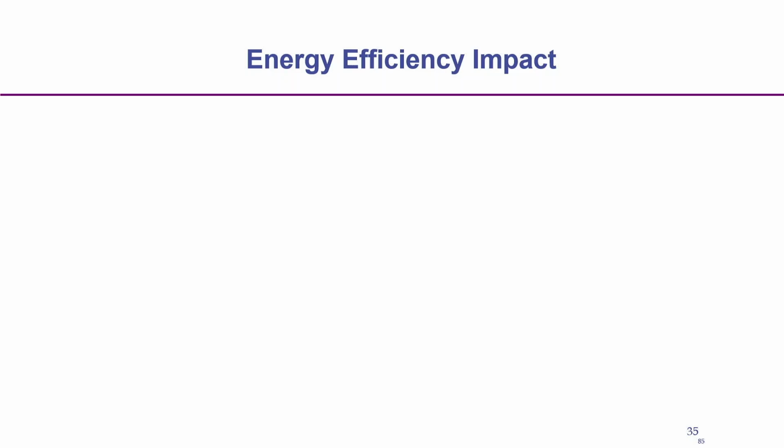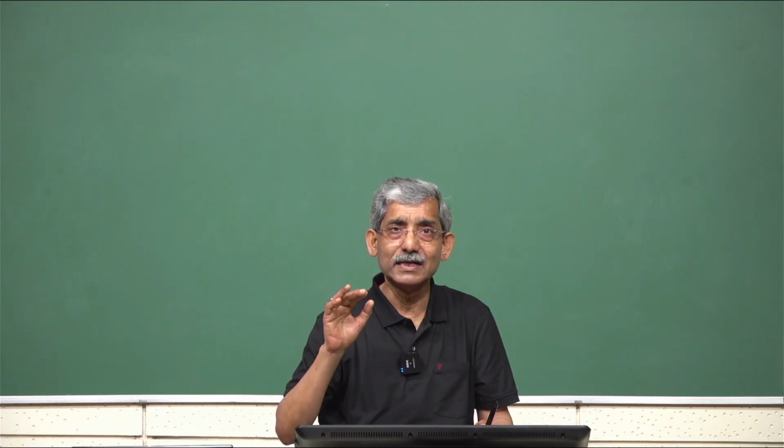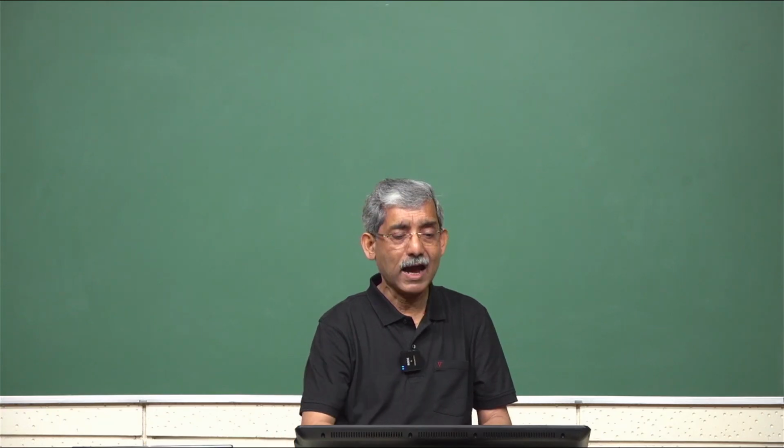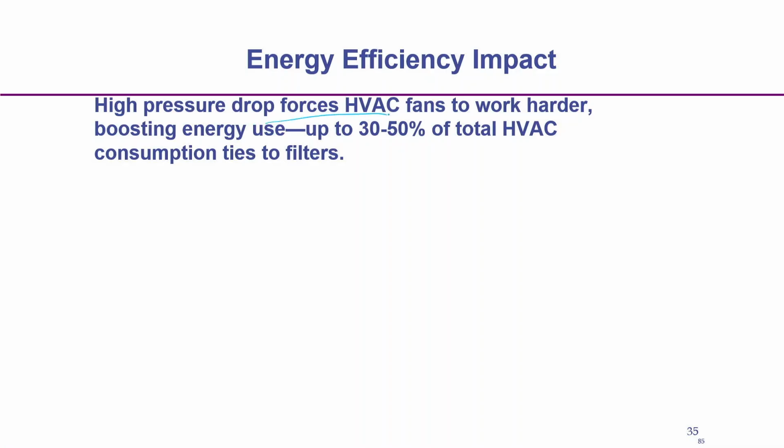So, energy efficiency impact. If the pressure drop is increased, it will increase the energy consumption. You can see a higher pressure drop in HVAC fans: the fan will draw higher power and have to work harder, and it will increase the energy cost.